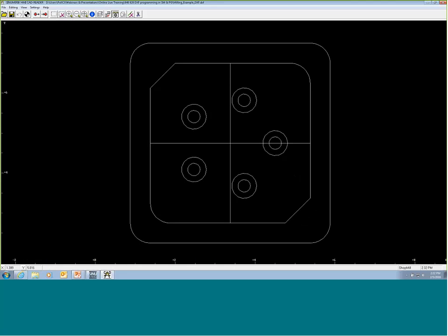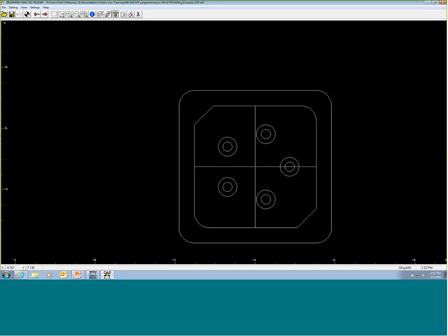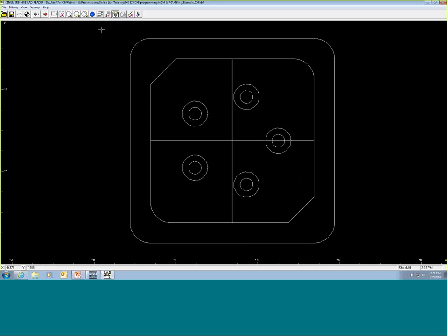Now, if I do need to get back out later, I can click delete machining range, and it will go back out. I can turn the dimension lines on. So even though I'm modifying things a little bit to make it easier to pick stuff, you can still get back to those values. Now, we have the little information icon, this is my geometry info. If I want to find out different things about entities, I can start to look at them.